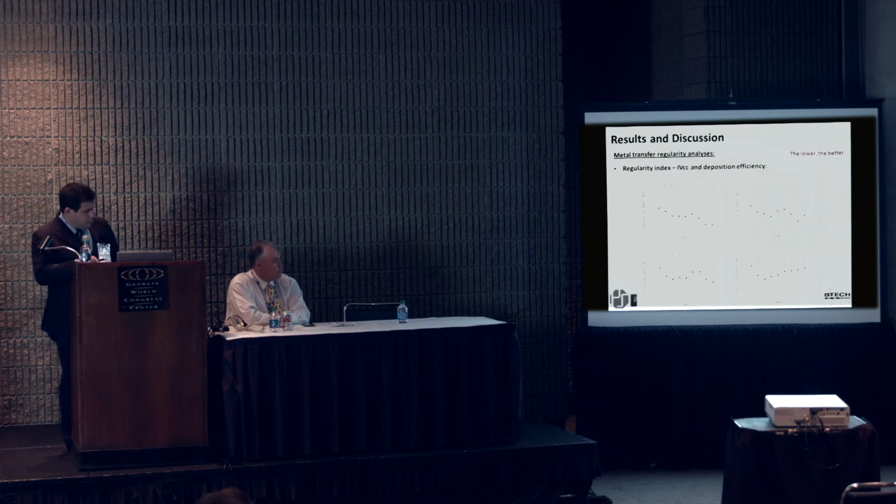But for the duplex, we can see some deep valleys here, so we may select a voltage range here. Here is too high a voltage, we have a cutting frequency here, so basically you have the three values. Here we have a valley, so we say, okay, for welding in such conditions, we end up with 17 volts, and here clearly another very small value, so that's where we should weld. Again, the duplex stainless steel has a more characteristic feature of low index values, showing where we should carry out our welding.